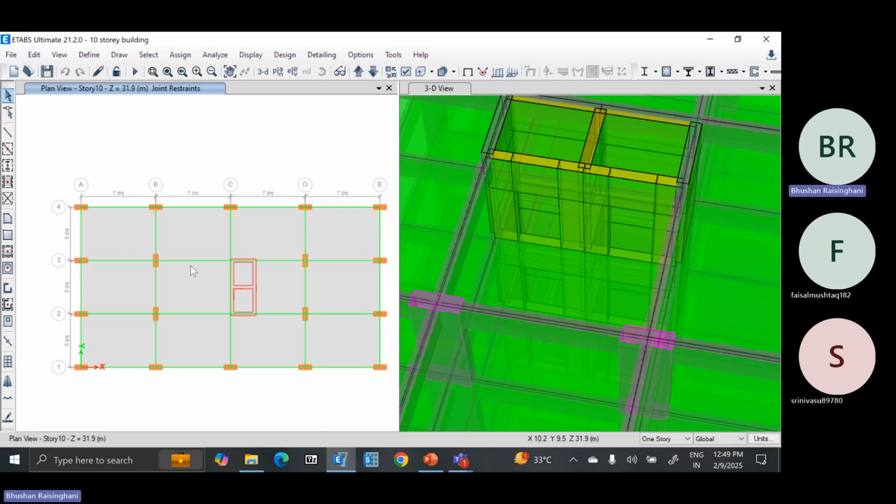So as explained to you previously also, you have to estimate in each particular direction. So this wall and this wall is in the y direction. These two walls are in the x direction. Sorry, three walls in y direction, two walls in x direction. So they will participate in a particular direction only. You have to consider that and then find the stiffnesses of the wall and the column and how much distribution is required for the slab.